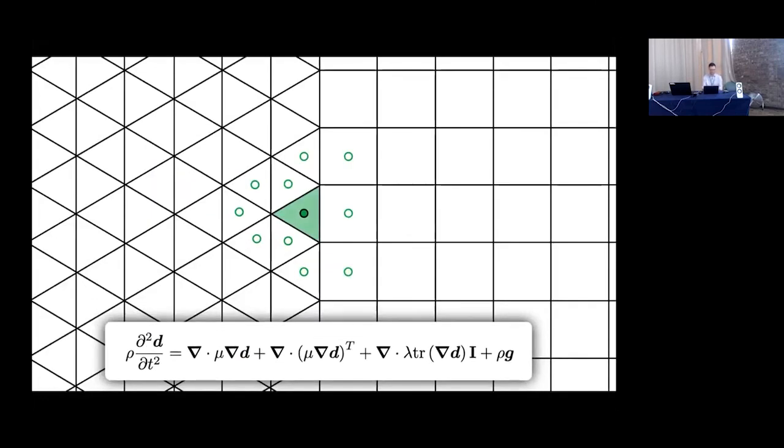There's a variety of solution methods implemented in Solids4Foam, as are available in many finite element formulations. You can do it implicitly or explicitly. If it's implicit, you can do it segregated or block coupled, or there are lots of things you can do. So maybe it's worthwhile reviewing some of these concepts. For the finite volume method, there are two things to note if I take a typical cell. The shaded area is your integration volume, that's what I'm going to call it. We take the equation on the bottom, or any partial differential equation, and we try to enforce it on that piece of volume, that finite volume.